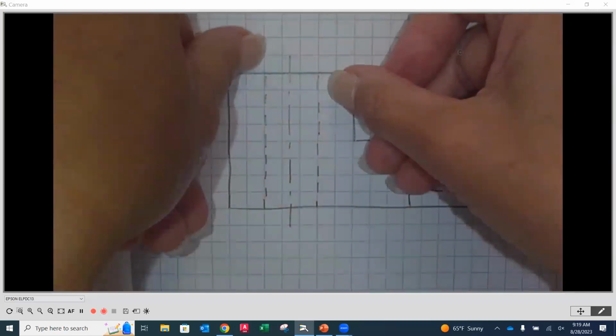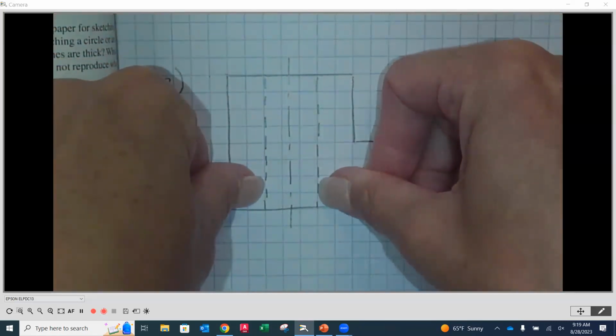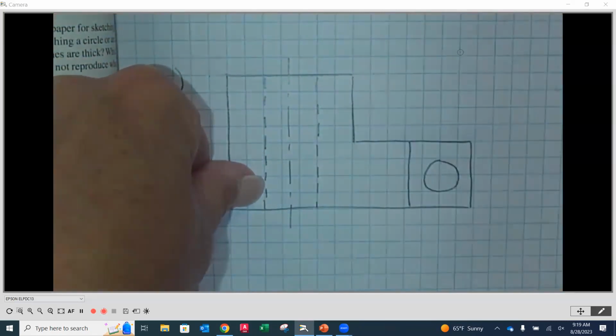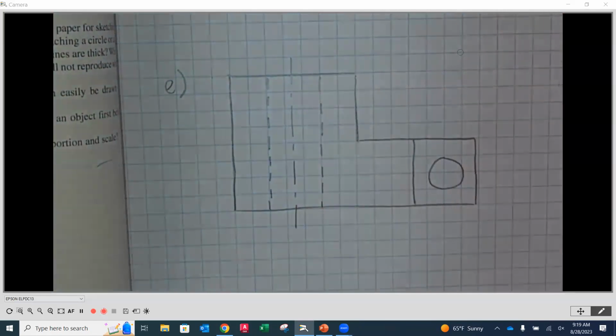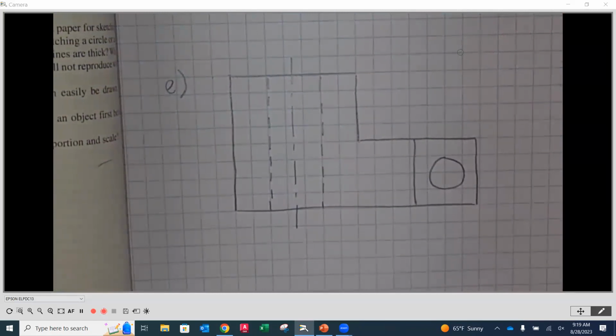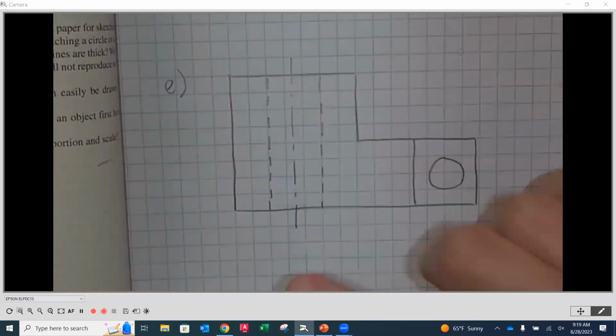And you'll notice that this would depict the width or the diameter, either side. And then we put a center line through it to let people know that's a circular feature. We only put center lines when we have a circular feature. That's showing us where that center line is passing through. If I wouldn't have the center line going through there, then it would be, for instance, like a square edge of some sort, that I'd have to then probably have another view to look at. But this tells me that's a circular feature going through there.